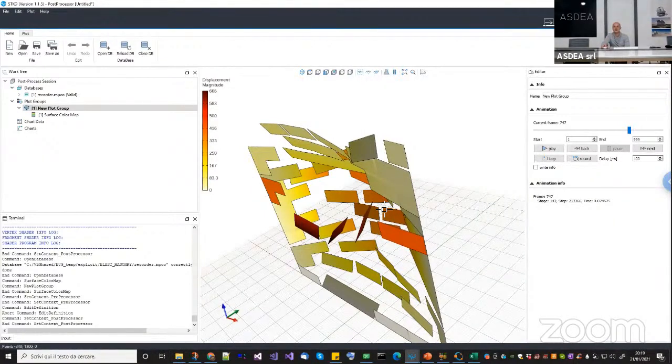The Tcl script that I've written here should be modified in such a way that it starts the analysis with an implicit solver, and the first time it finds a huge nonlinear problem, it switches to explicit dynamics. I didn't think of it, but yes, it can definitely be done.